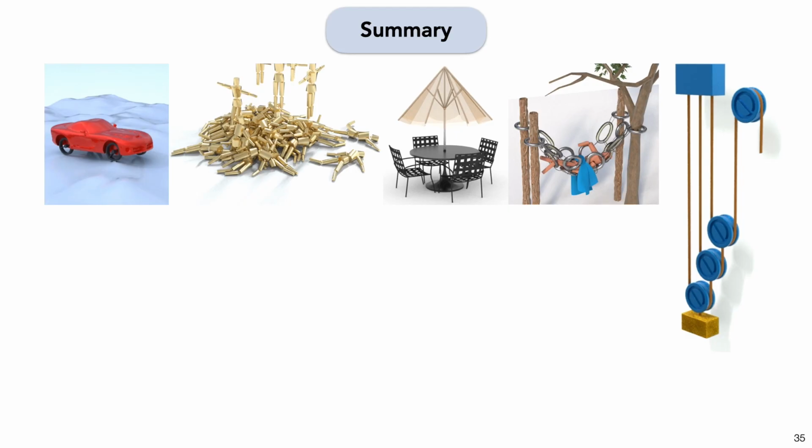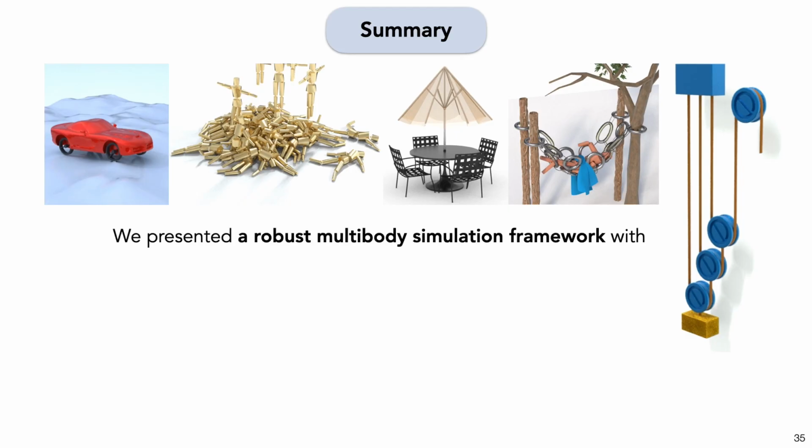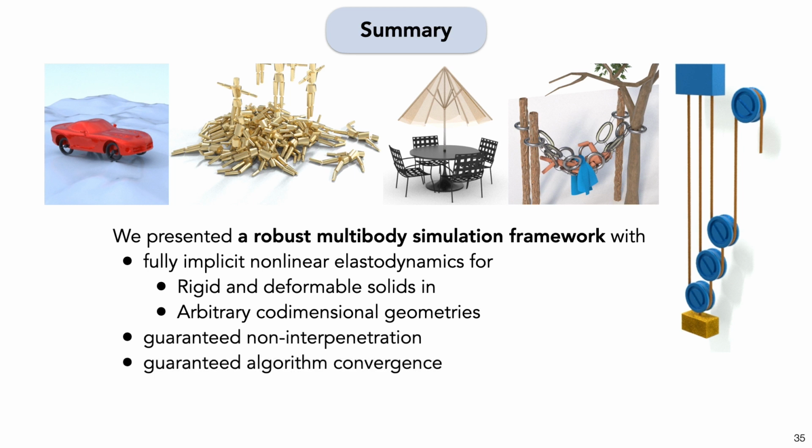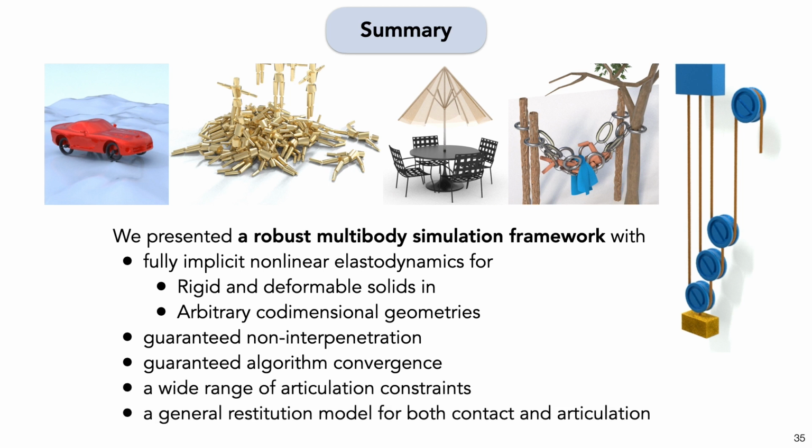In summary, we present a robust multibody simulator with fully implicit nonlinear elastodynamics for rigid and deformable solids in arbitrary codimensional geometries. Our simulator guarantees non-interpenetration and algorithmic convergence, and supports a wide range of articulation constraints with general restitution model for both contact and articulation.